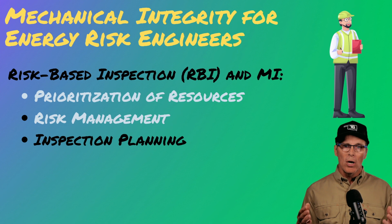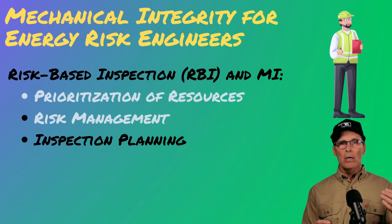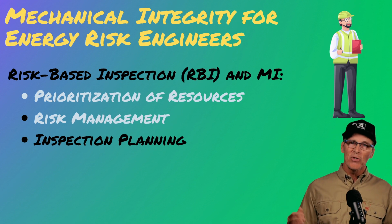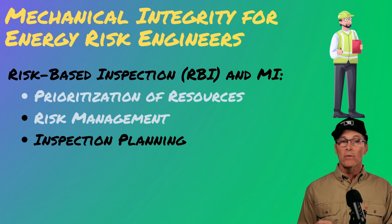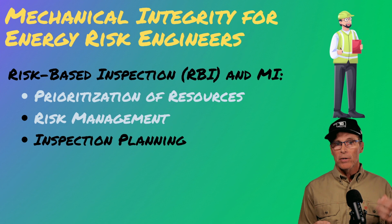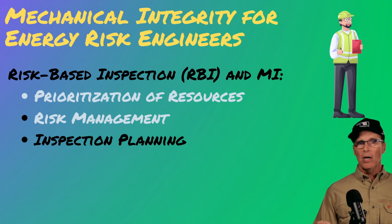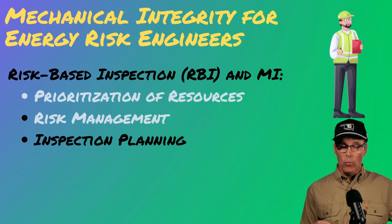Inspection planning helps in an RBI system for planning the inspections to work around your equipment. You have to worry about outages or shutdowns, turnarounds. Different industries call them different words for the same thing, basically for either repairing, regenerating, getting the unit back ready to run again. But that's part of inspection planning, is that you can't just do a once a year inspection all the time, because the equipment may not be available. It may be part of an entire process that's not available for whatever reasons.